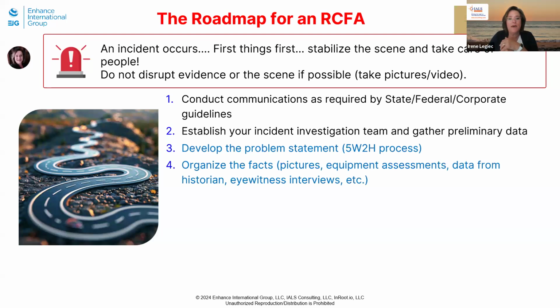You want to organize the facts. So don't just have a literal dump of data on a slide. Really organize it. Get your pictures together, understand the equipment assessments, get the data from the historian, have the eyewitness interview. So spend a little time doing your pre-work so that when you walk into the incident investigation meeting, you're well prepared and it runs smoothly.